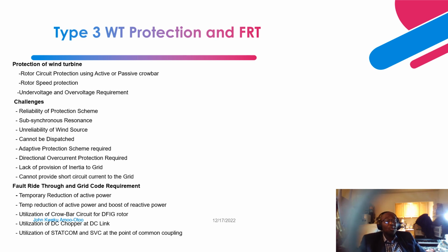As such, a lot of these coal power plants are being decommissioned, and these are many synchronous generators that provide inertia to the grid. Synchronous generators providing extensive inertia to the grid helps to strengthen the grid. When there's a fault on the grid, because of the inherent inertia that the generators' rotating mass provides, it limits the rate of change of frequency from decreasing at a faster rate.